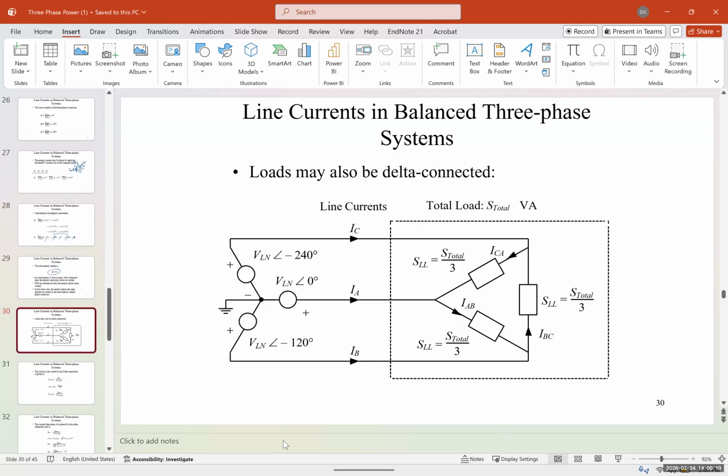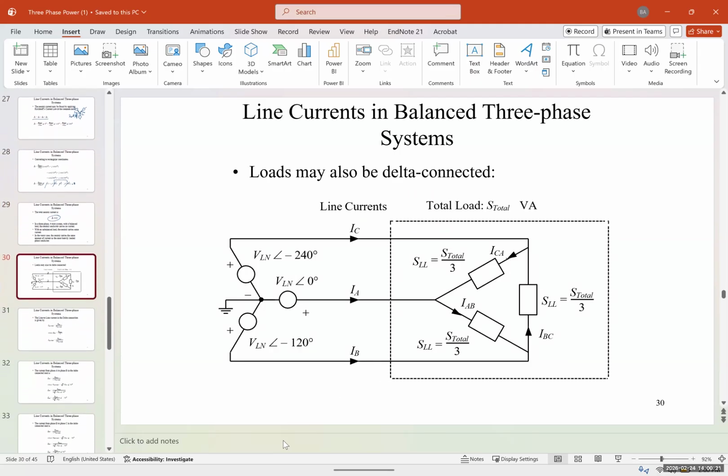But for larger motors, you need to be able to ground them. So if something goes wrong, one of the phases is disconnected, the additional current will go through the ground and you'll be protected. And when it connects to the ground, it creates a spike in the current, and the fuse or the breaker would just pop.